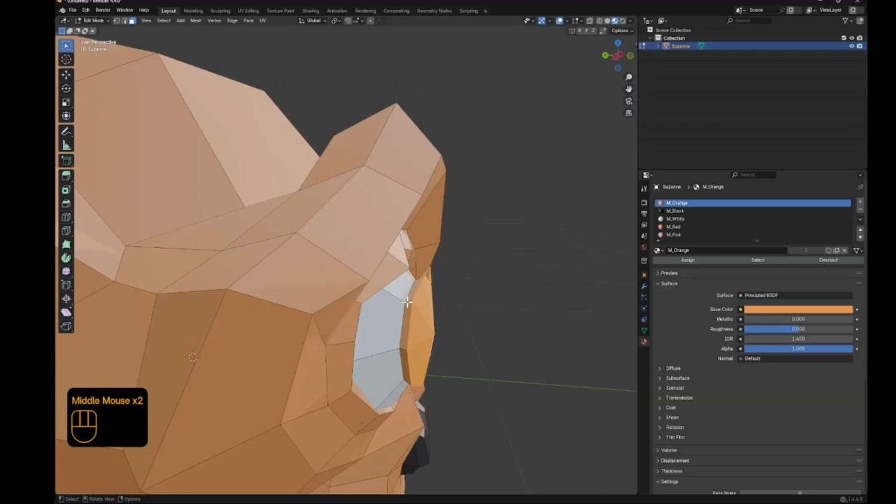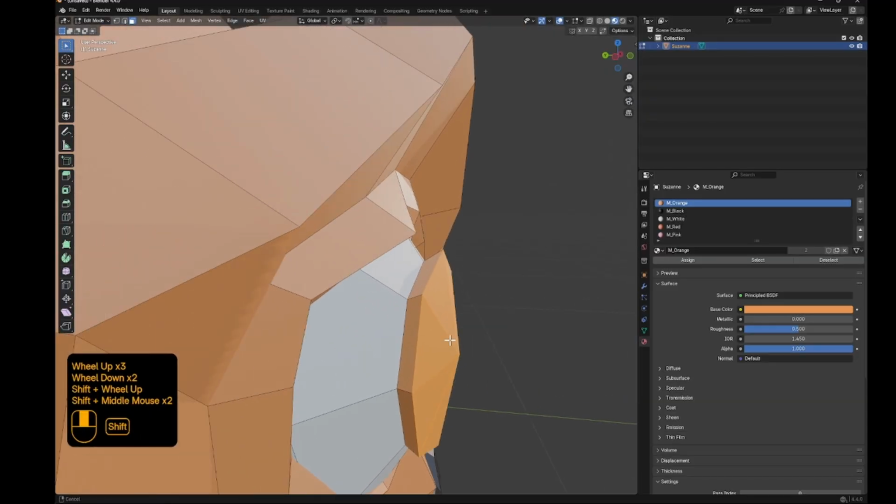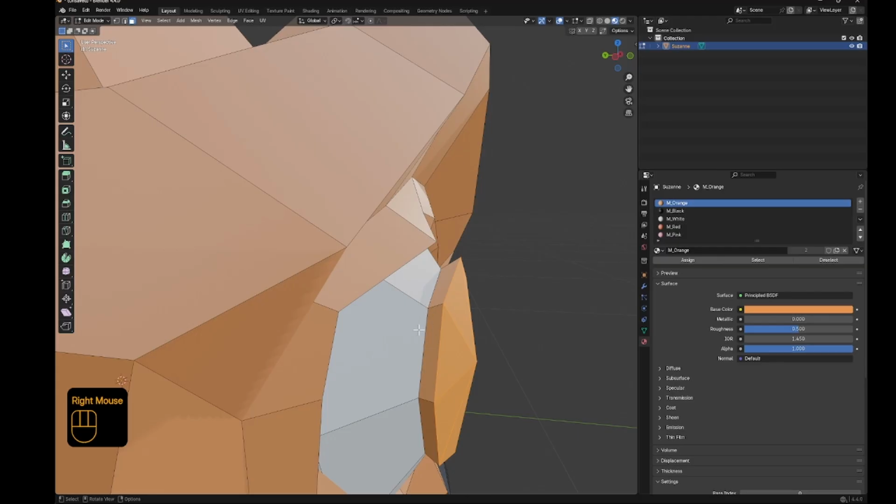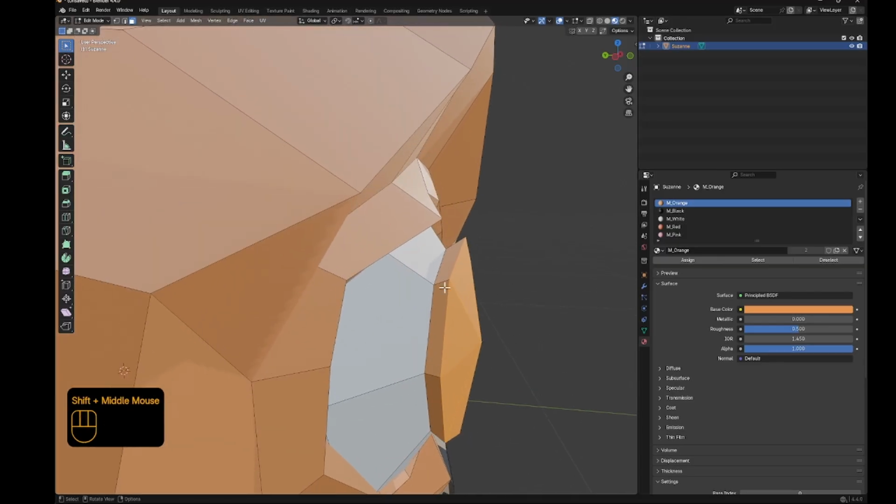And then what we'll do is if I just hold the mouse here, so if you remember when we did loop cuts, let me just show you with Control and R. You notice if I go this way, so I'm on this edge, the loop goes along like so, okay? And then if I come up to this edge, you can see the loop goes around, and that's the direction those faces go. If I just right click to stop that a second, we can select them almost the same way that we would loop cuts by holding Alt. So if I bring my mouse over to this edge, not this long one here or this long one here, come to one of these shorter edges, they'll direct it around the correct way by pressing Alt and left mouse button click. You'll see it selects all the way around.